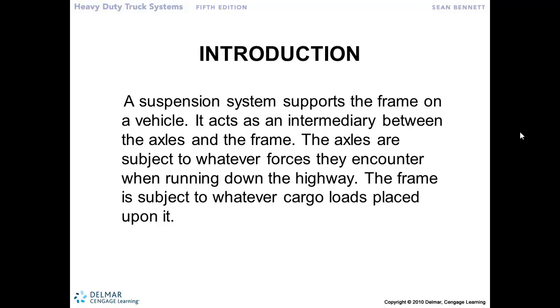So all of these different systems are carrying the weight and the load of the truck. And each supports it in some way, but the suspension allows movement between the axles and the frame, whether that be because of additional load put on the truck or bumps that the suspension hits as we're driving down the road. The suspension will allow movement between the two while still holding contact with the tires onto the pavement.